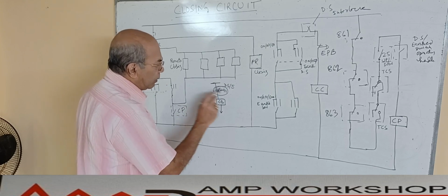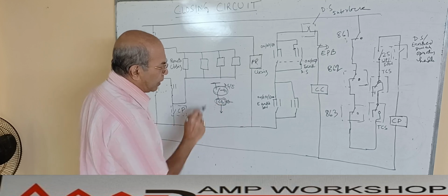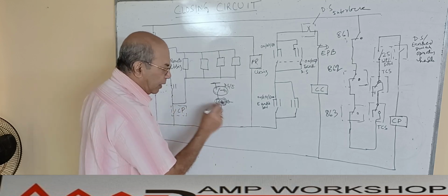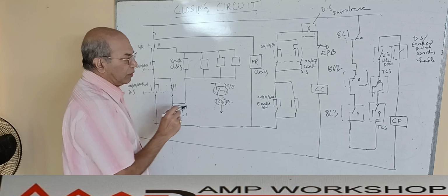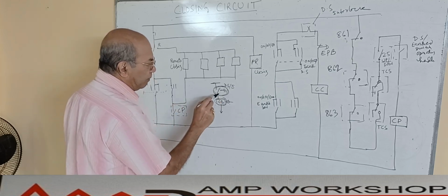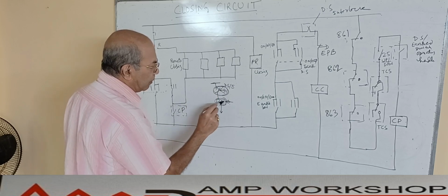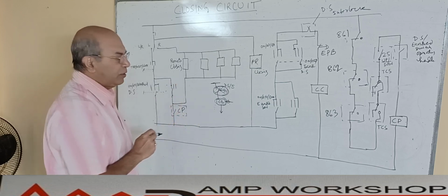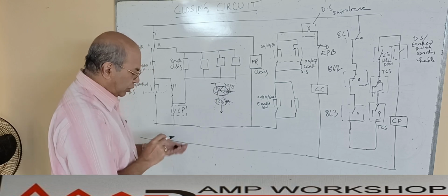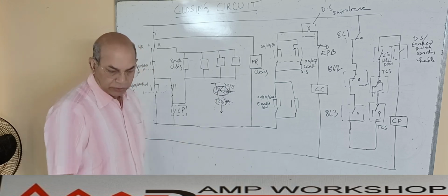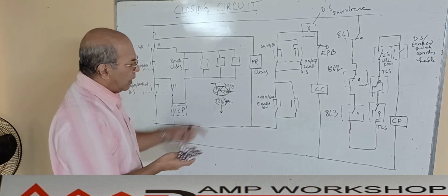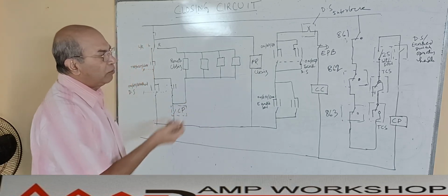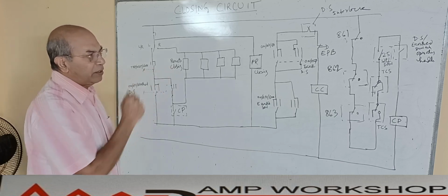When the disconnector is not there, the circuit breaker is a withdrawable type, where it has 3 positions: connected, test position and disconnected position. If the disconnector is not there, then the circuit breaker's disconnected, test or connected position shall be taken into consideration instead of the earth switch position. I have shown this to highlight why this interlock is required. Whatever interlock is required in the closing circuit with the disconnector, we will be discussing here.